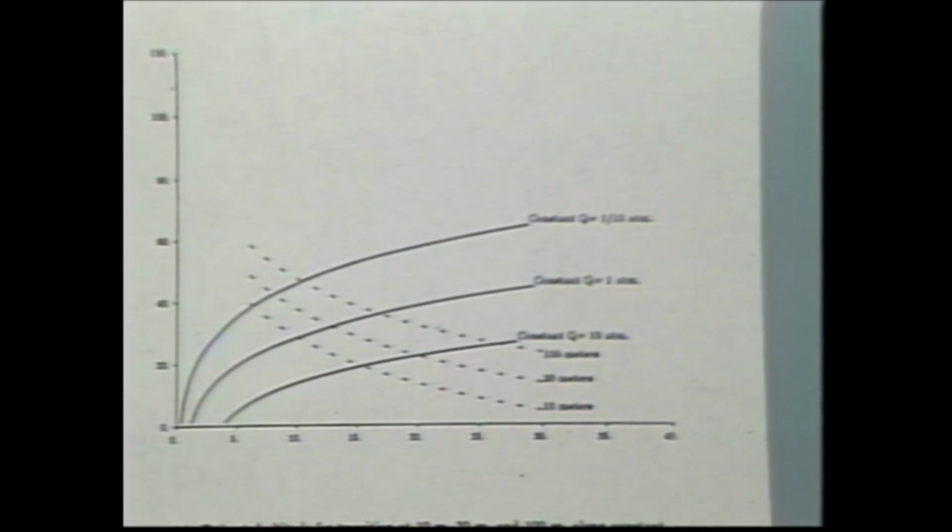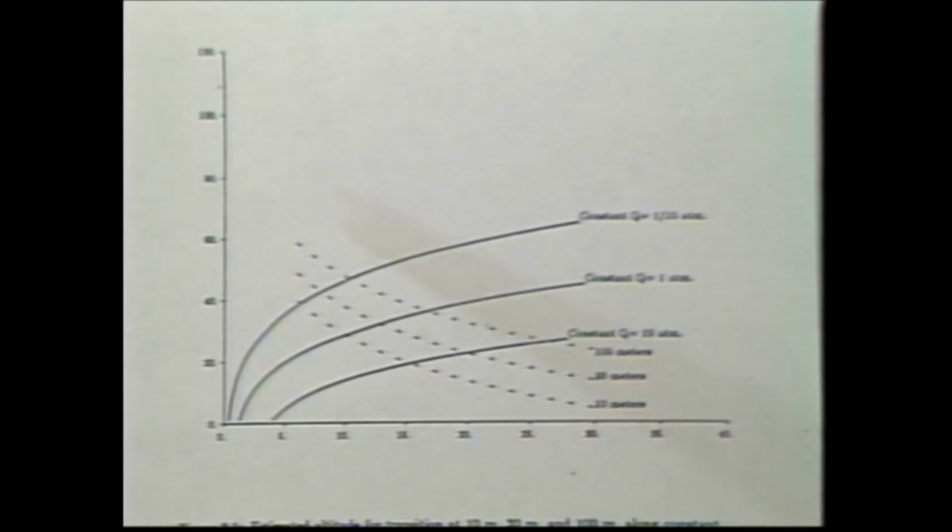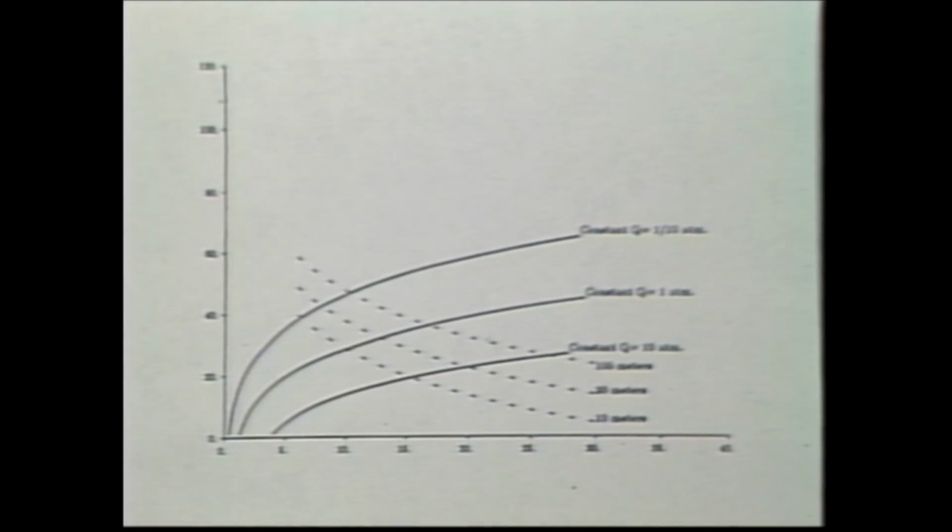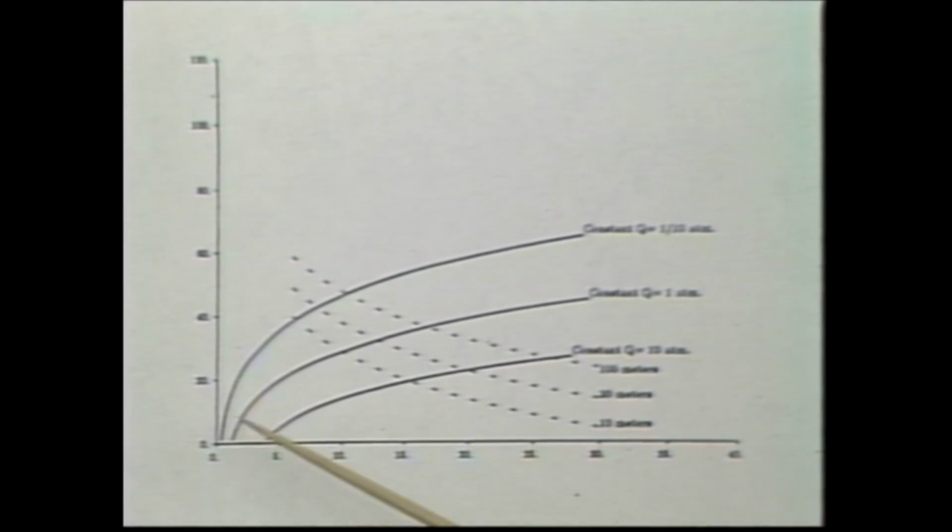Using that data, though, we can estimate approximately what regimes we'll be in for the boundary layer coming in on the undersurface of a hypersonic vehicle. What I have shown here is a plot of altitude versus Mach number. And on this plot, I've superimposed 3 trajectories which are calculated for constant dynamic pressure. This isn't to suggest that that's the best way to fly a hypersonic vehicle, but it'll give you an indication of what we're talking about. Generally, we can expect that a hypersonic vehicle, in order to provide sufficient performance in the engine, is going to be flying at dynamic pressures higher than about 1 atmosphere. So we're probably talking about a vehicle that's in this range right here.